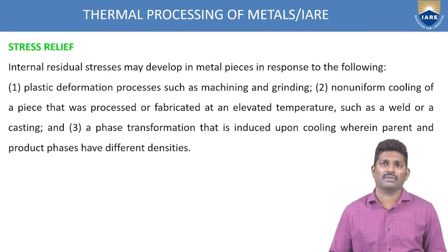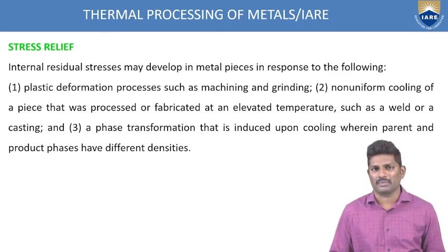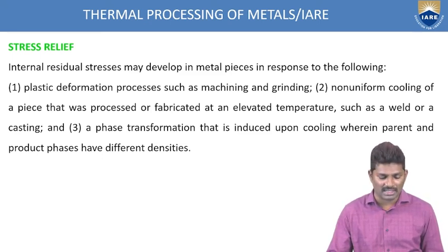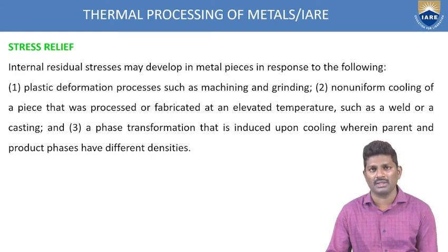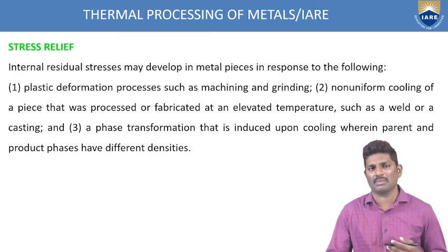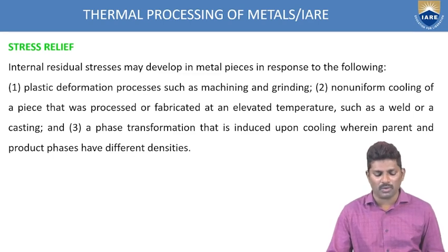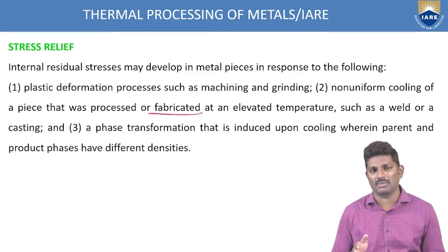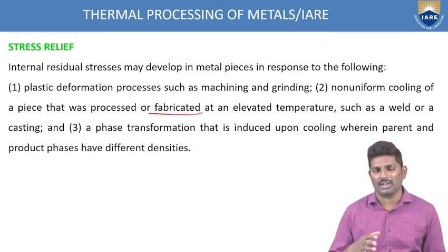So why stress relief? Internal stresses are subjected to the body during the action of forces. These internal stresses can be relieved during the annealing process. Plastic deformation processes such as machining and grinding cause some deformation, and this deformation can be relieved with the help of the annealing process. Non-uniform cooling of a piece during the fabrication process, if a proper cooling is not done, again causes some change in the fabrication. So that's why this has to be elevated to some temperature in order to relieve all those stresses.